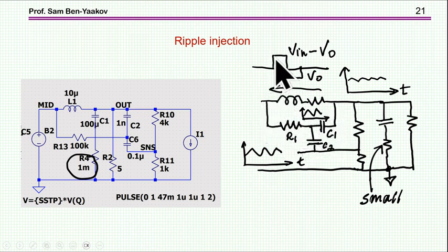So now I have this voltage on this R1, C1, which is causing a triangular ripple here, due to the, of course, you have to choose correctly the R and C values to have this ripple here. Now the whole thing is riding on the output, so you have a DC here, and you don't want to inject it to this point, so this is like a coupling capacitor to get rid of the DC, so you just inject the ripple part to here, okay? By this, you can have here a very low ripple, or almost no ripple, while you actually inject the ripple here.